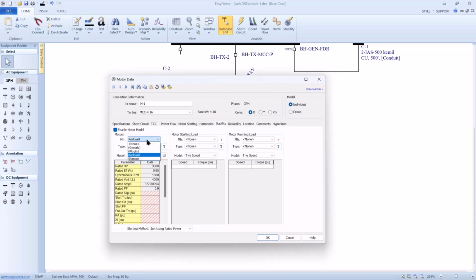library additions that we have, and it's worth going through the part numbers to see what matches up with what you're using. I'm going to use generic for a standard induction motor, and I'm going to bring in all those parameters, including transients and subtransients and time constants.